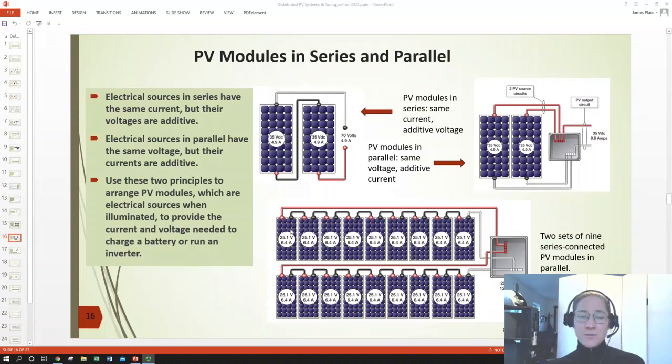So this is an example of something where we have multiple cells in series. So you can imagine 2 of these panels with multiple modules in series, and then the two panels, the upper and the lower, themselves are in parallel. So we can up voltage by putting things in series, and we can supply more current by putting things in parallel.